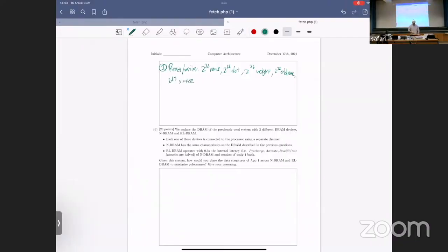So what happens during a row buffer conflict? What is the formula? The formula for calculating the cycles is first the cost of row buffer conflicts, how much time it takes to serve them. So we have row buffer conflicts multiplied by what? In a row buffer conflict we first need to pre-charge, and then we need to activate a row because we have an open row policy, right?